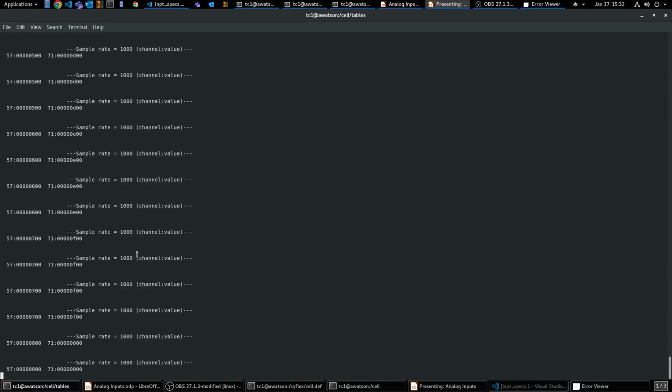Again, this is my dummy driver, so the values that I'm looking at right now are garbage, but on your system you might see something that's more meaningful. If you see 0.000000, and you know that the voltage should be reading 1, and it's being streamed as a float, it's not working.